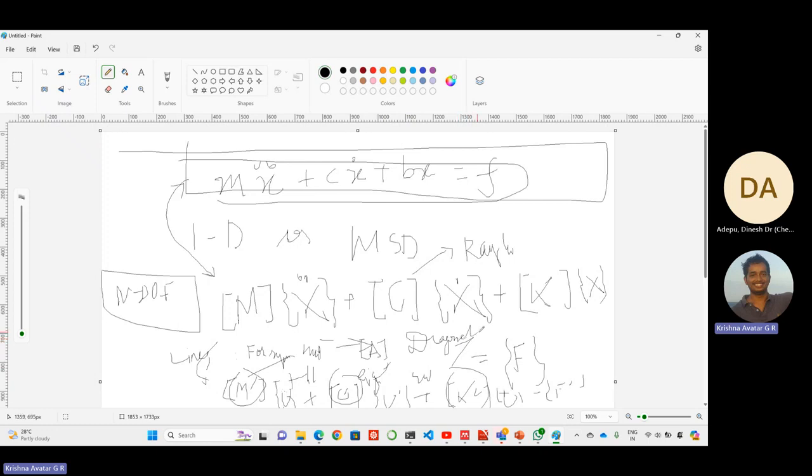Now you see it's a very nice reduction: if these matrices are diagonal, then you have just n number of ODEs, n ODEs which are uncoupled. Once it's uncoupled, you can use all the theory from the 1D oscillator. We solve n ODEs independently, then assemble and project it back, and we have gotten the solution to this problem. So that is the beauty of the 1D system.